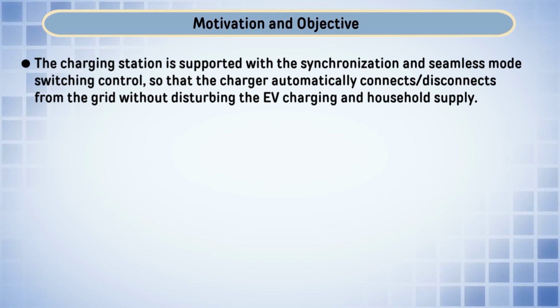In case of standalone, we need one converter which could be controlled in voltage control mode, where after converting this DC into AC, at the point of common coupling where various loads are connected, we need to maintain voltage and frequency. However, in case of a grid connected charging station, the voltage source converter which is utilized for DC to AC conversion is controlled in current control mode.